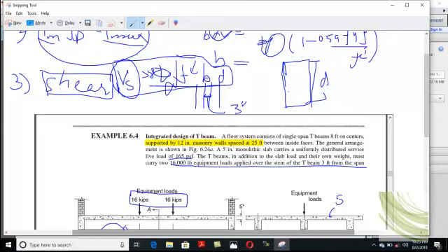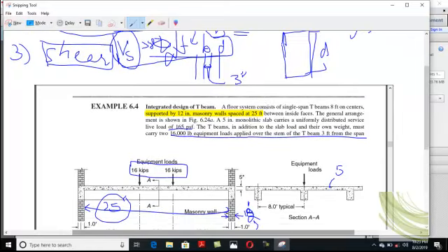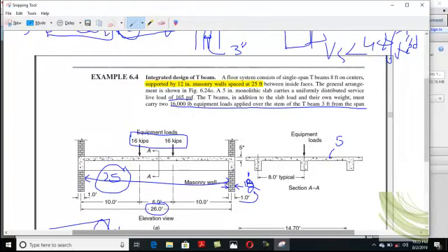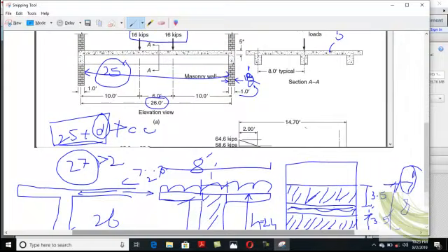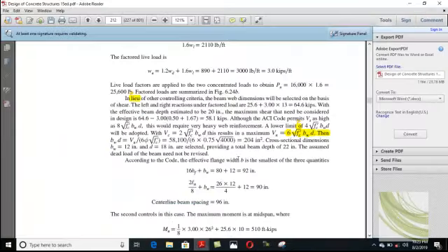So in that case we need to revise our dimension. So basically, your depth should be such that your Vs must be less than 4 phi fc prime into bw. Clear? And when we are designing our footing, we check this depth from beam shear as well as from punching shear. So here basically the depth criteria is satisfied from shear.